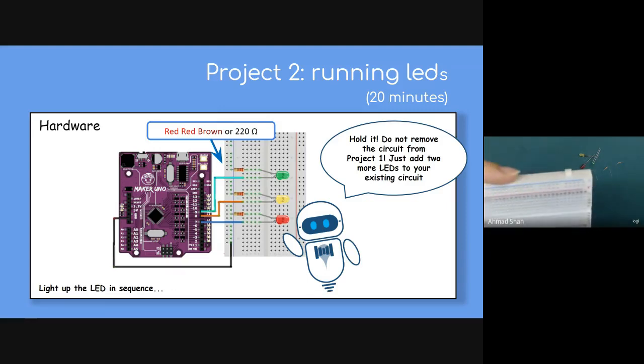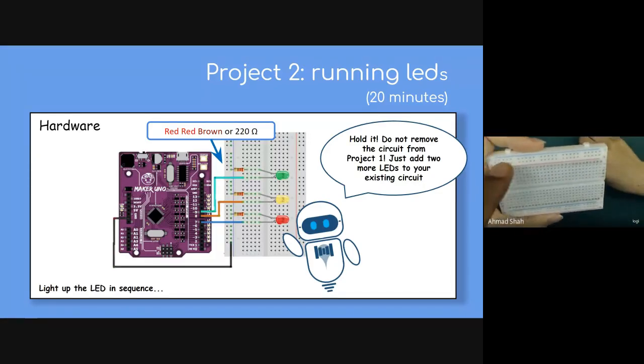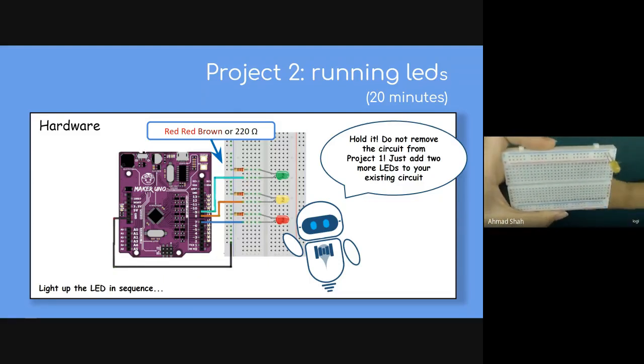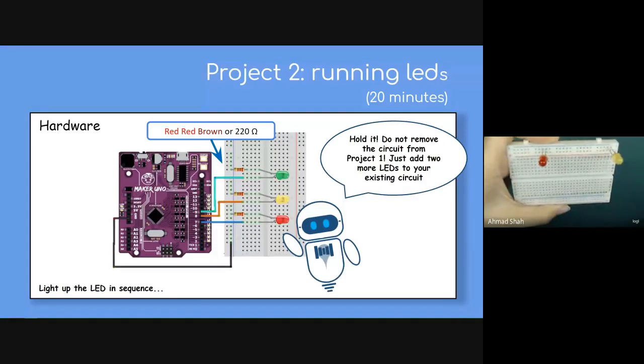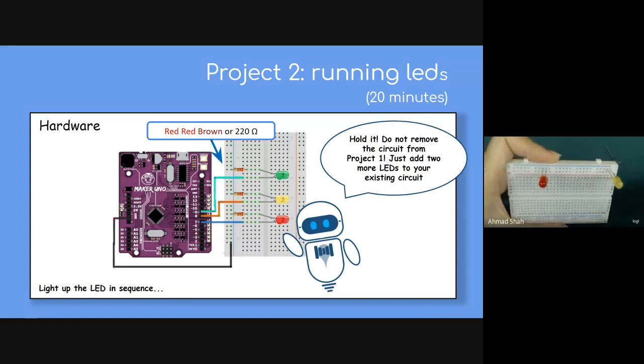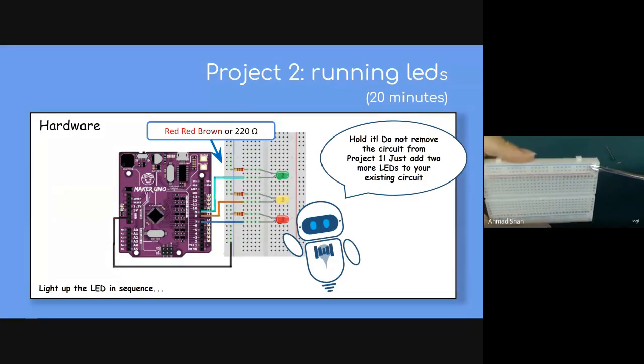So what she meant is the holes, the pinholes throughout the negative terminals. You can see this is the negative terminals. All the holes inside already have a thin metal plate which connects each one of them. So if you put an electric wire at the first pin, the current can flow until the end of the pin along the negative. But it won't jump to the positive pole. It will go along the negative only.